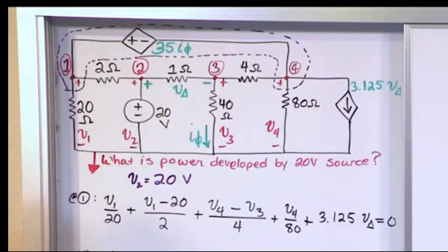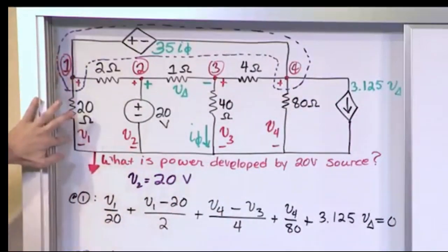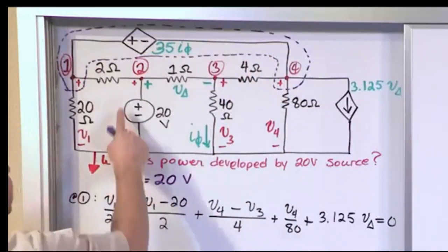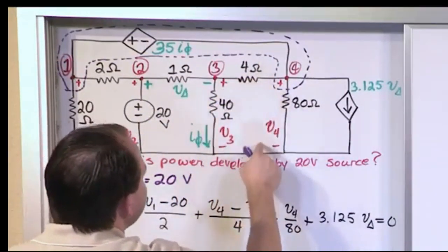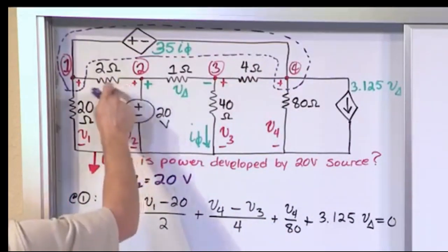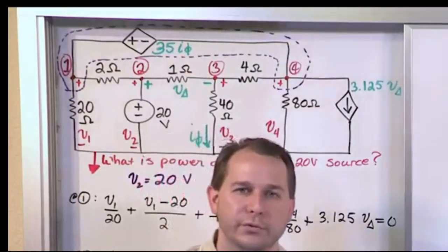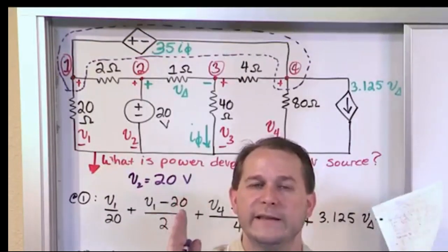Would you not agree that the voltage between these 2 points would be the node voltage that I measure here minus the node voltage way over here? It's the same thing we do internally here. You go up to V3 minus V4, that gives you the voltage drop across this resistor. Over here it's V2 minus V1, that gives us the voltage drop. When you subtract 2 voltages, it's just telling you what the voltage difference is between those 2 points in the